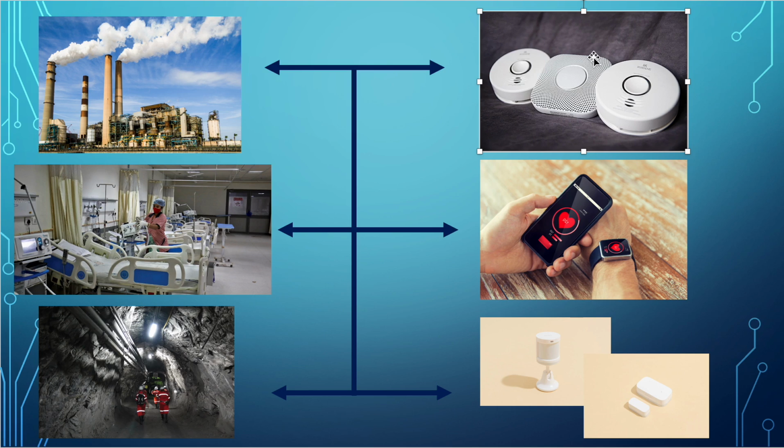While digging and continuing the dig, the machines will hit air pockets and release dangerous fumes like methane, which, if overdosed, will kill people. To stop that, it is necessary to monitor the purity or compatibility of the air inside the mine at all times. So smoke detectors or air particle detectors must be used inside mines at all times to guarantee safety when mining takes place.